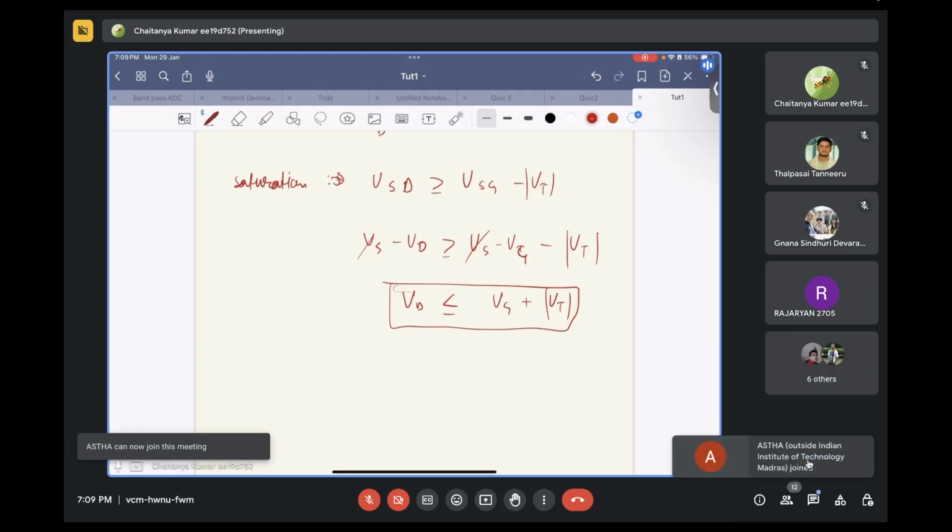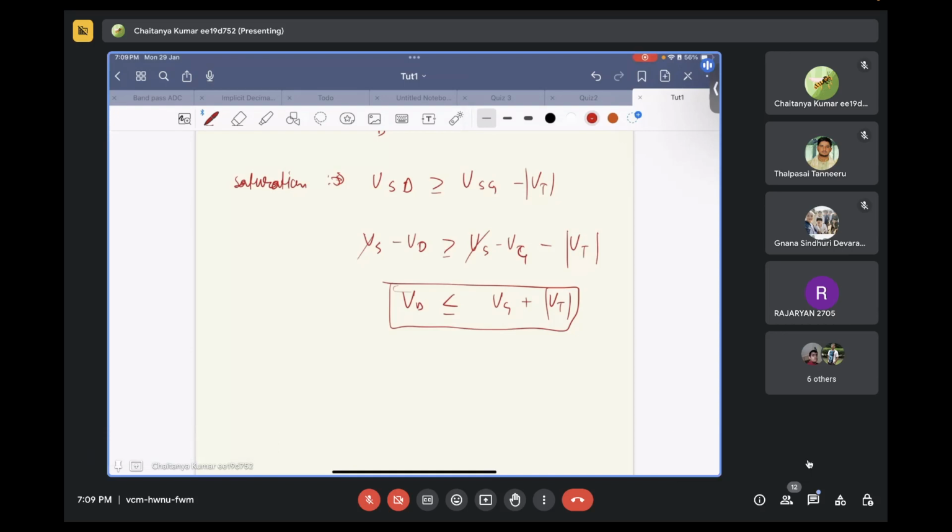By diffusion, I mean let's say the charge concentration at one point is higher than the charge concentration at another point. So a charge concentration difference is created, and your electrons move from the higher concentration to lower concentration. That is called a diffusion mechanism.